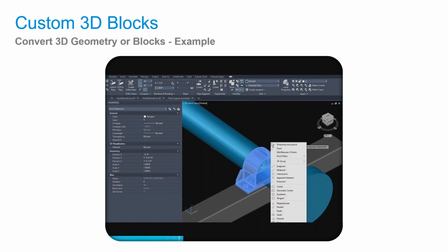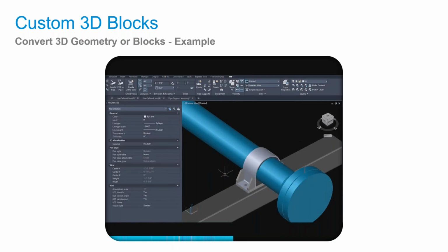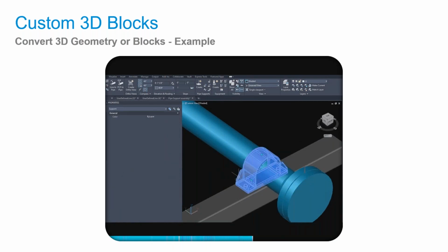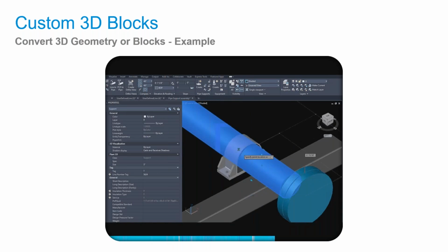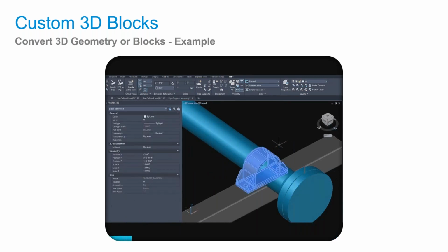In order to create such on-the-fly supports, you will need to place them on a pipe. If you don't place them on a pipe, they will not get created. But still, you can use them on a different pipe later, and you can make copies and so on, but you need to create them on a pipe. So that's something you also need to know.